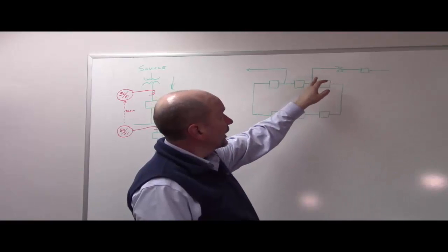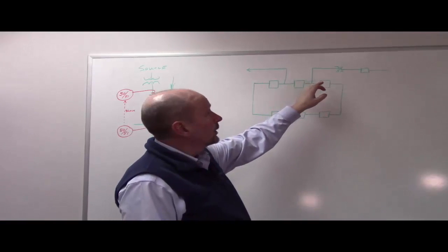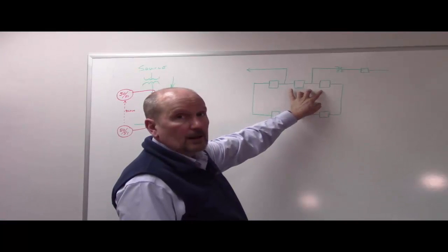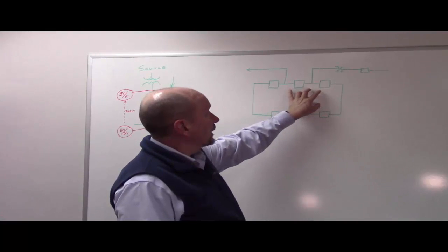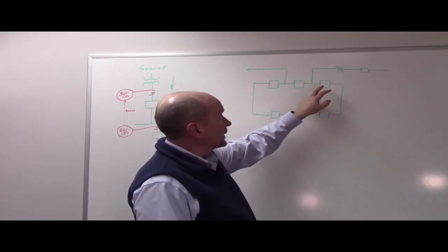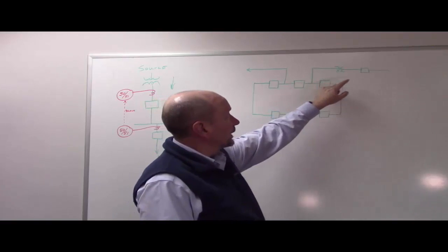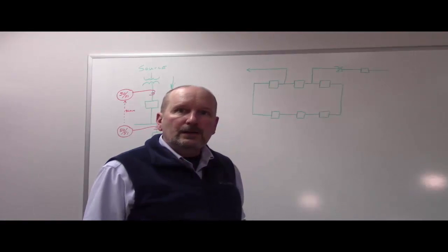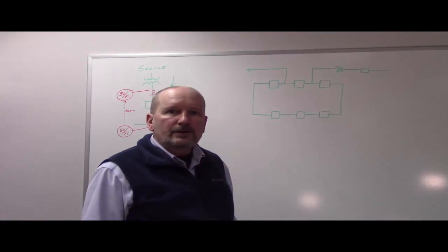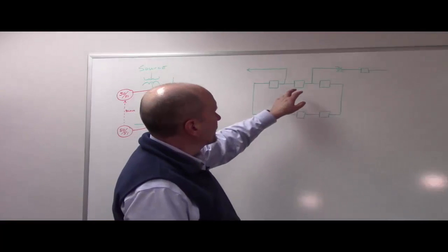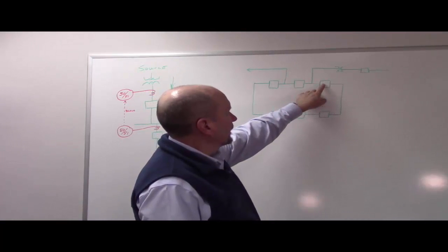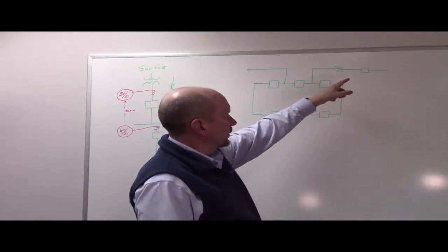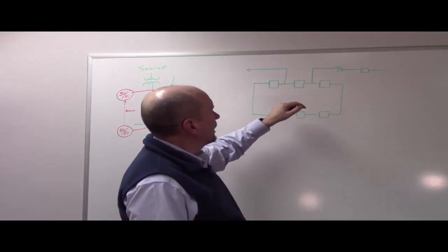Now, over on this side I've shown a transformer and low side circuit breaker there, and 2 breakers on the high side. And say there's a fault within that zone of protection, so we have to trip these 2 breakers and this low side breaker. Okay, what happens if one of those does not trip? Well, say it's this breaker that fails to trip. Well, then we're going to trip the adjacents, and we've already tripped the low side. But say